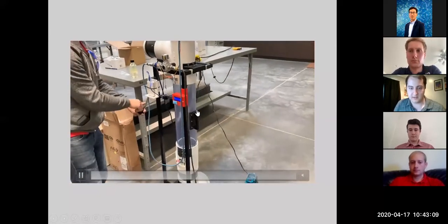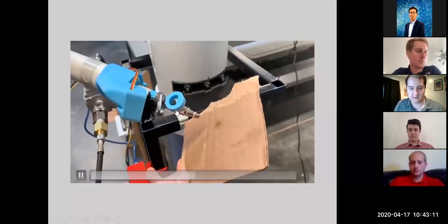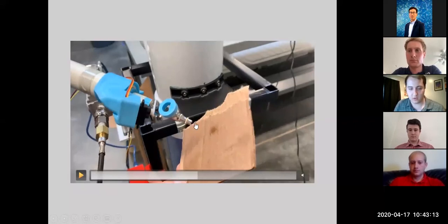And you can see the compressor hooked up right there. Next, this is just showing how it works, that we can actually spray. We 3D printed a little stopper right here to make sure none of the pesticide gets out and that they're able to hold a good amount of pesticide within the chamber. And here's the servo actuator that will press the button for however long we specify using the Arduino controller.